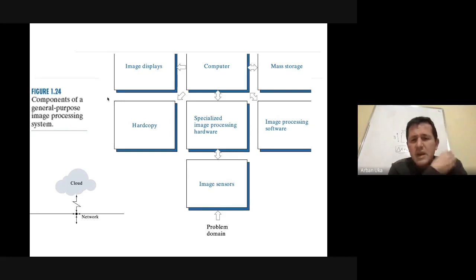Okay, maybe it needed a higher RAM. The RAM that it had was 4 GB. Probably this 4 GB of RAM could have been the threshold for being able to run smoothly, reading a model that is trained, which are these HDF5 files. Maybe it was not powerful enough to read the trained model, run it, and test it on an image that we insert later on. Probably the Raspberry Pi could not do it. Most probably a Jetson Nano can do it.